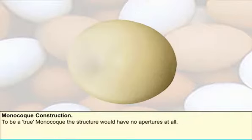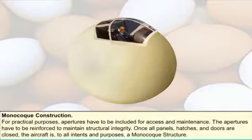To be a true monocoque, the structure would have no apertures in it at all, but for practical purposes they have to be provided for access and maintenance. The apertures have to be reinforced so that the integrity of the structure is maintained. Once the aircraft doors are closed and all the hatches and access panels are fitted, the fuselage is, to all intents and purposes, a monocoque structure.